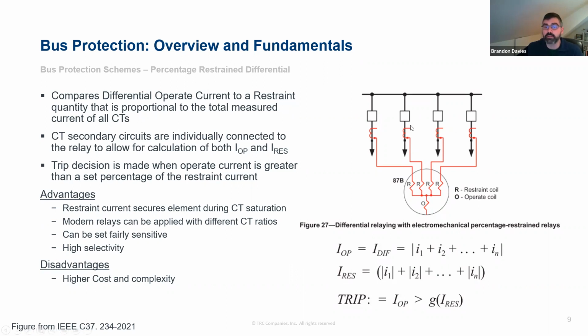So if we had this same example up here, and we've got the fault on the leftmost equipment here, external fault, and we had 1,000 amps of current coming into the bus on each of these other lines or transformers or what they are, you'd have 1,000 amps of current going in times 3 and 3,000 amps of current leaving the bus.